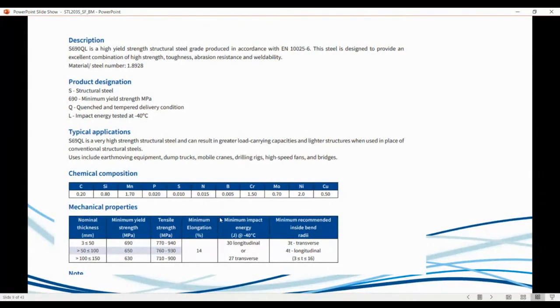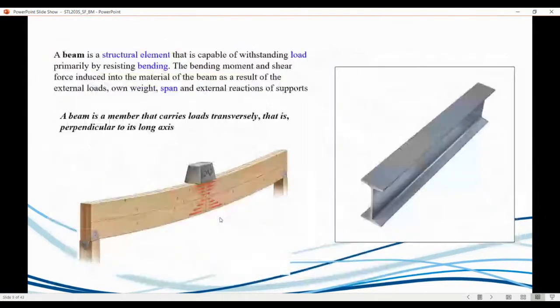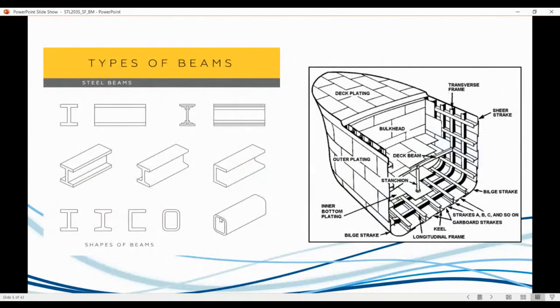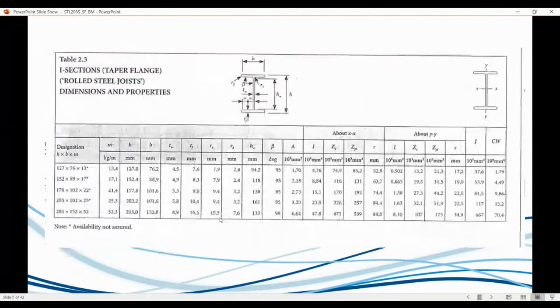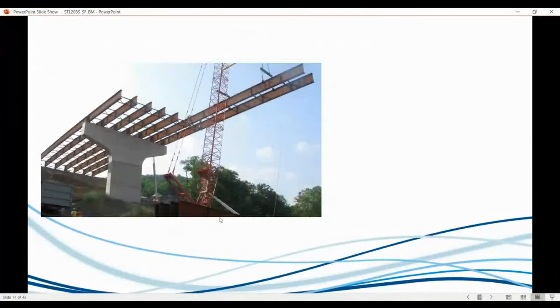Yeah, they give you examples, but just in essence, you've noticed the more strength the steel gets, and that's probably to do with more carbon, the elongation decreases substantially. However, they're still considered ductile. They're also impact tested at minus 40 degrees, right? And they can withstand that. So just to summarize, all these sections, the so-called beams, can be made from those varying steels, right? So let's move away from material science now.